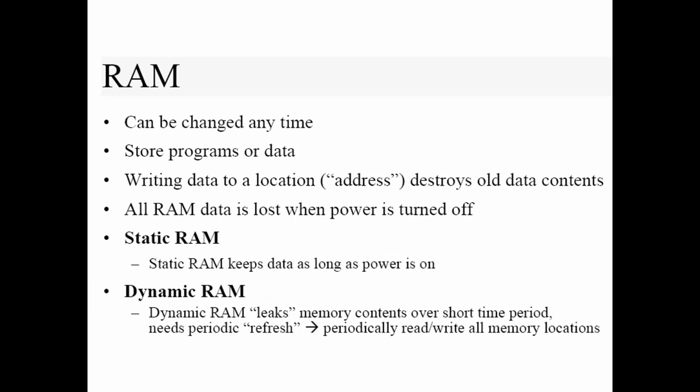So we have the static RAM, or SRAM, characteristics of which are faster and more reliable than DRAM, but more expensive and consumes more power. In terms of usage, it is often used for cache memory and small amounts of high-speed storage. Another is the dynamic RAM, or DRAM, which is slower than SRAM but more cost-effective and can store larger amounts of data, and is commonly used for main memory in embedded systems.